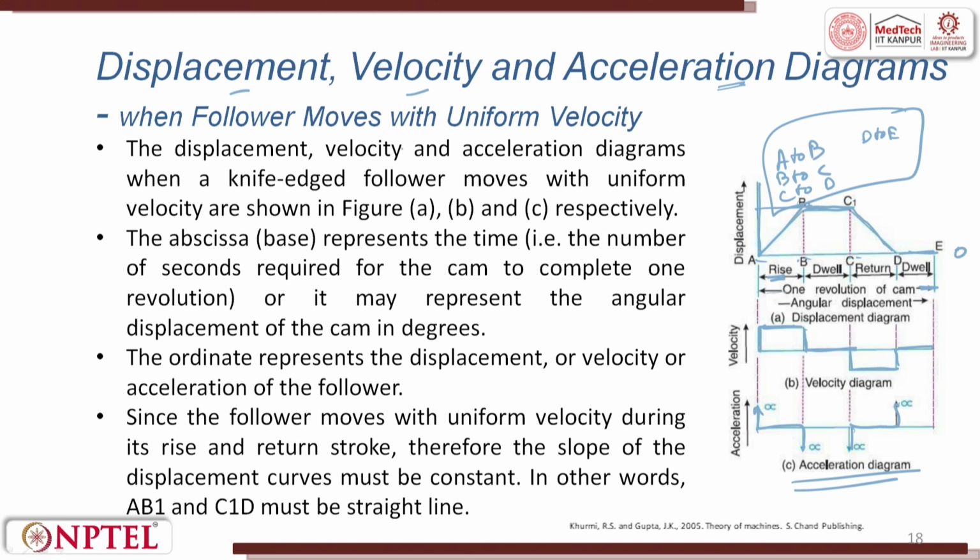So, when the follower moves with uniform velocity, the displacement, velocity and acceleration diagrams, when a knife edge follower moves with uniform velocity, are shown in A, B and C. The abscissa base represents the time, either the number of seconds required for a cam to complete one revolution, or it may be represented as the angular displacement of a cam in degrees.